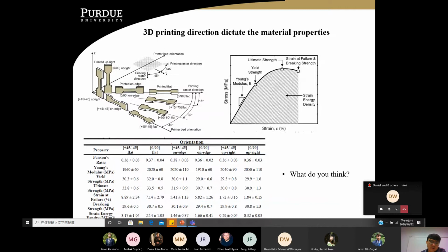One of the questions I typically get is about designing, and I just want to quickly talk about this. It also ties in with your FEA analysis. A lot of you first design a model and then 3D print it. One of the things I keep saying is that it really depends on the direction in which the 3D printer prints. A lot of people jump to the conclusion that the material is not strong enough.